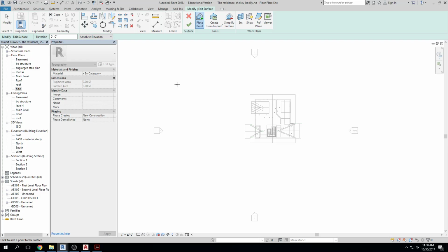You don't generally draw your topo surface right in your Revit model for complicated projects. You draw two separate files and you link them together, which is a better way of going about it. That means the coordinates from one file have to coordinate with the coordinates from another file, so it's kind of complicated. We won't wholly get into that, but I wanted to say it so that if you ever work with these and somebody's doing that, you'll know why, okay? But on the topic today of very simply creating these with some slope, we're going to do that.